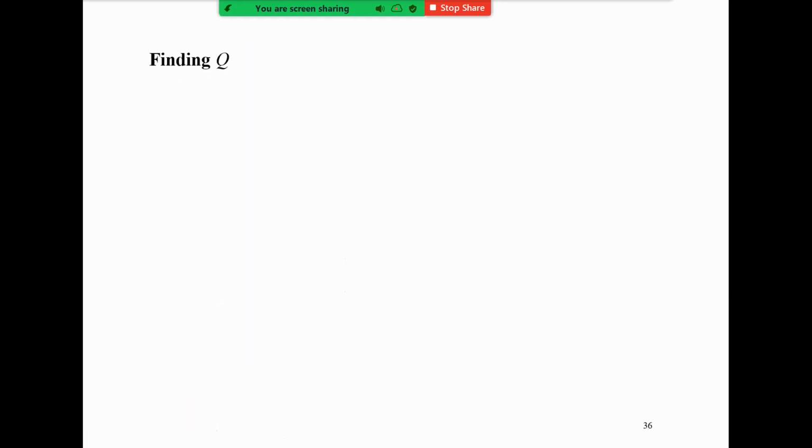All right, let's just go through some examples for you to be familiar with how we're going to find out the least common denominator for the unstable factors. Okay, here we say the reference signal is a step, right? Here, this is the disturbance. Okay. And what is Q? So what is the least common denominator of the unstable factors? What is Q? If you compare s and s times s plus 1.